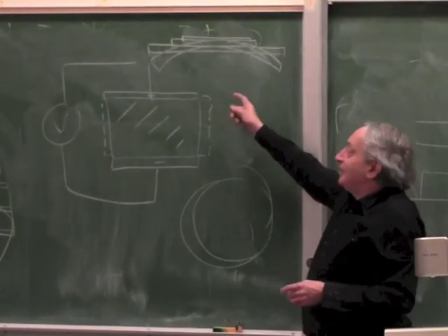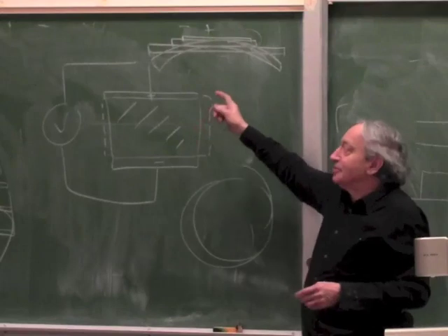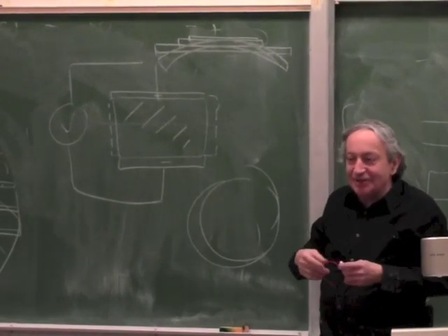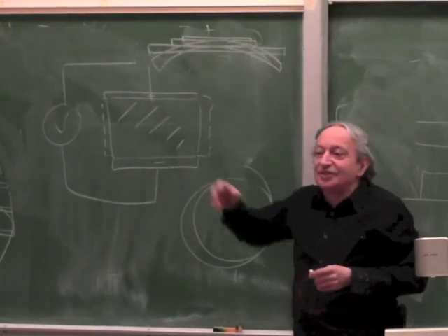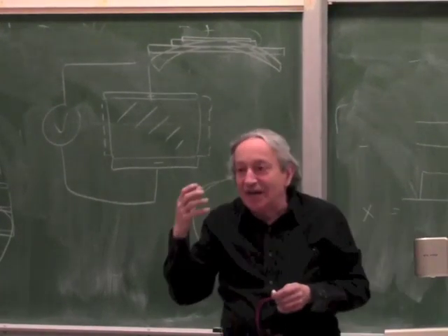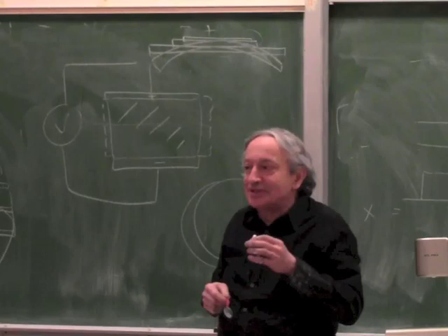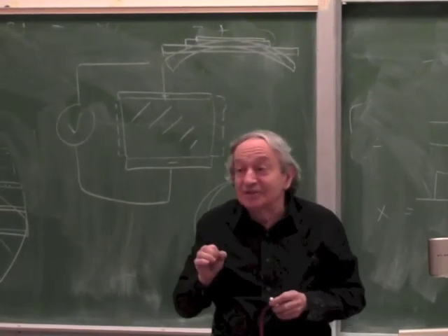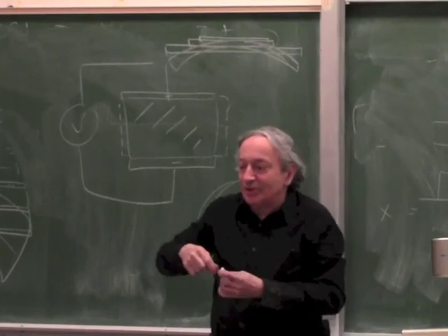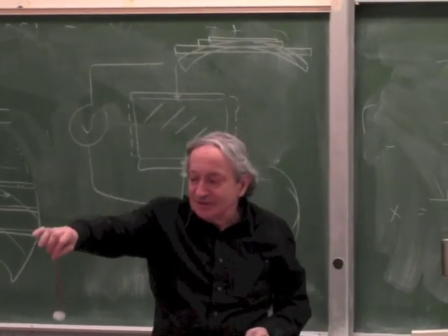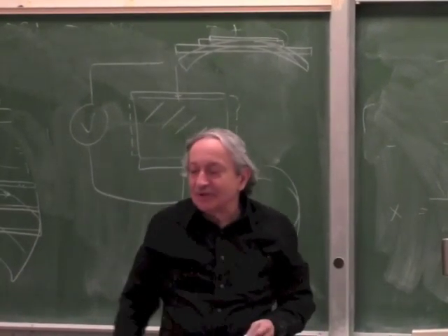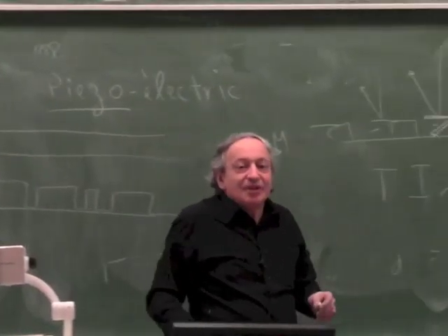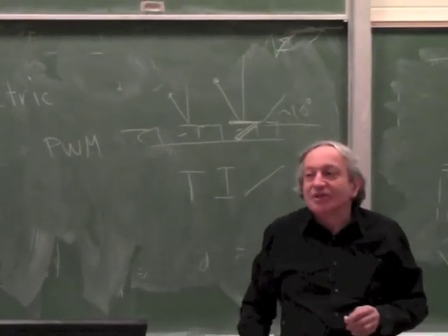Typically, it's driven by a few kilohertz, because of its mechanical resonance. You're trying to drive it at its mechanical resonance, and because these things are stiff, their mechanical resonance is high, so they always make this annoying sound. Especially because they're small. If they're small, their mechanical resonance is high. So pass it very quickly because the lesson is coming to an end. Just have a look at it. You can identify the 2 electrodes in the piezo. Just pass it quickly. So these are piezo actuators.